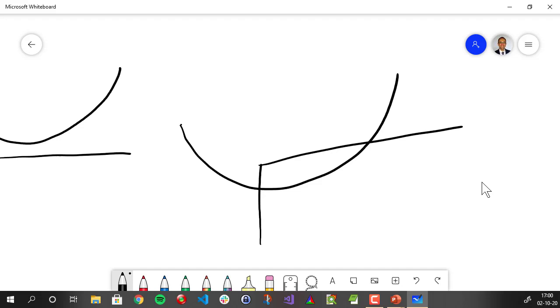It means that at a particular moment, your mesh can be inside the tool, because you have seen that Metafor computes the equilibrium by trial and error. The configuration of your mesh changes iteratively in a Newton-Raphson procedure, and it is corrected as long as the equilibrium is not reached.